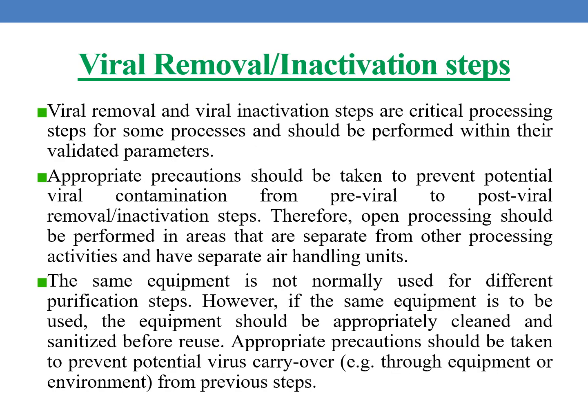Coming to viral removal or inactivation steps. Viral removal and viral inactivation steps are critical process steps for some processes and should be performed within their validated parameters. Appropriate precautions should be taken to prevent potential viral contamination from pre-viral to post-viral removal or inactivation steps. Therefore, open processing should be performed in areas that are separate from the other processing activities and have separate air handling units in order to control the microbial count in the environment.